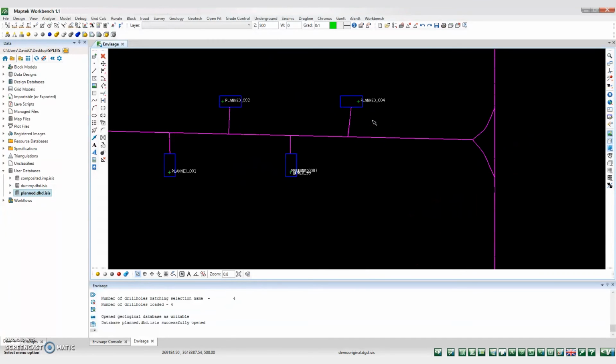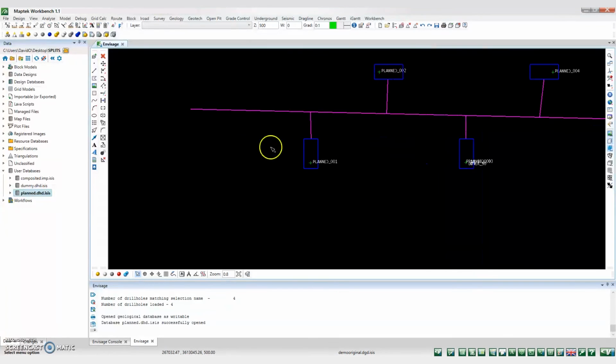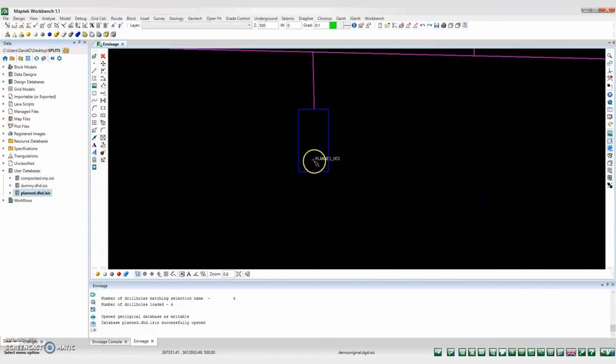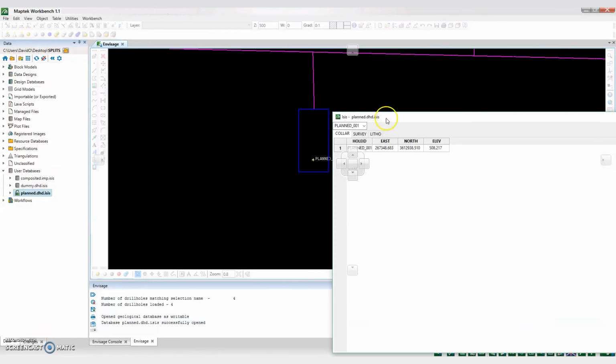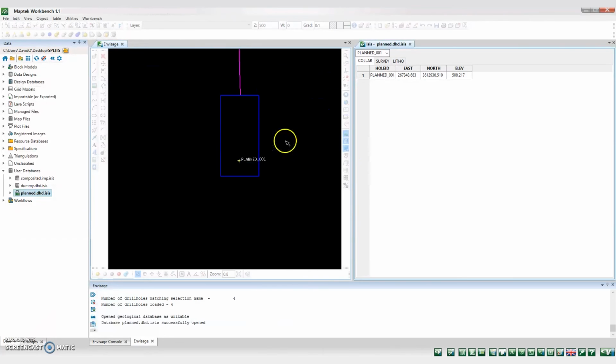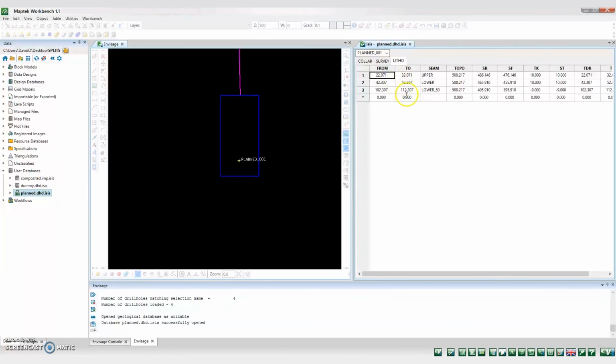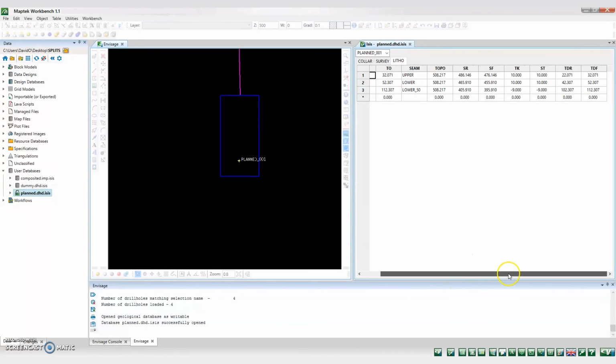Now that they're drill holes, we can use them with any of the other functions in Vulcan that work with drill holes, so we can view them in Eureka additionally. Or I can just go edit them in the database here, make any changes I want to the litho manually or through the usual drill hole editing tools.